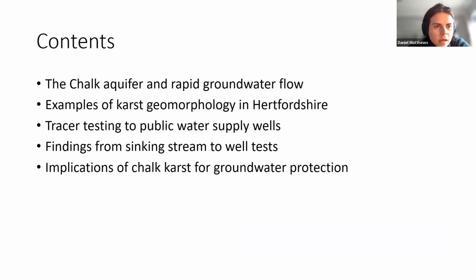Okay, so I'll start by talking about the chalk aquifer a little bit in general and the importance of rapid groundwater flow through the aquifer. Then we'll have a look at some examples of karst geomorphology in my field area in Hertfordshire, and then move on to talk about why trace testing to public water supply wells is such a good method to study karst in the aquifer. And we'll have a look at some results and talk about some implications for groundwater protection.